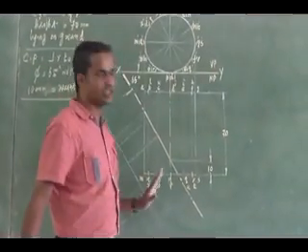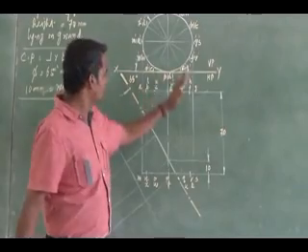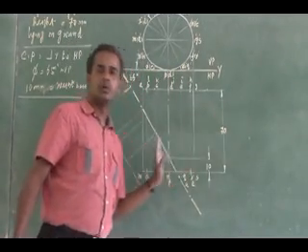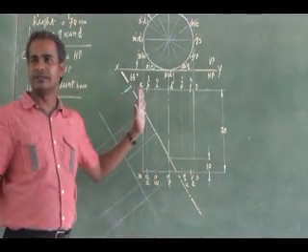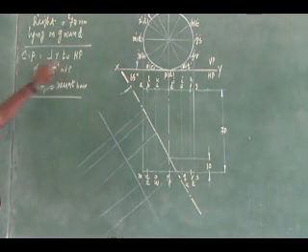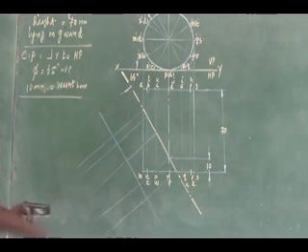Now, for the projection you have drawn, you only show the axes and the generators in the top view, right? Then the cutting plane you have to represent. See, the cutting plane data is this. The cutting plane is perpendicular to HP.